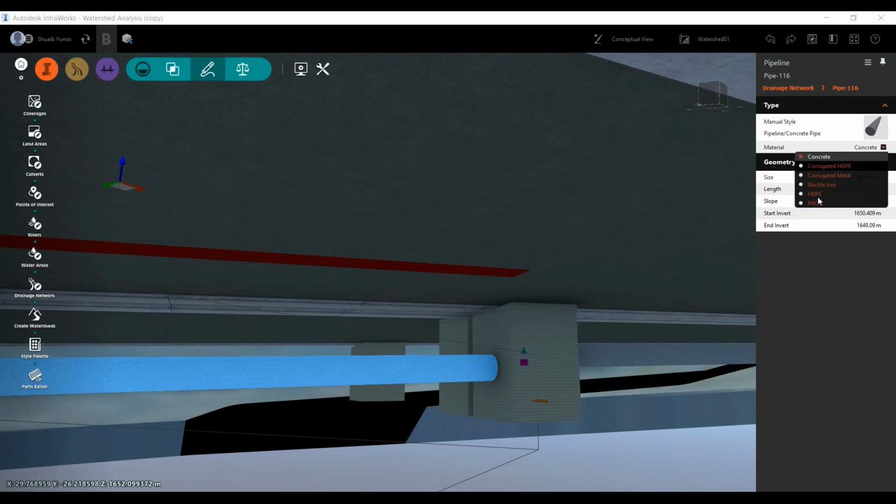You can go and change the type of material. However, for stormwater, we normally use concrete. But in terms of other things, you can go and customize it, HDPE, all of those things. Again, the sizes also you can go and customize. Everything is fully editable here. And the cool thing is it gives you your start inlet and your end inlet.